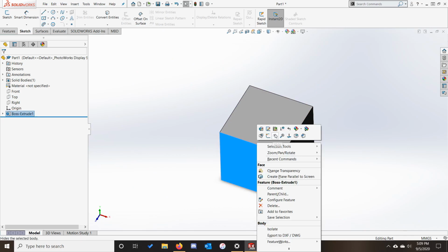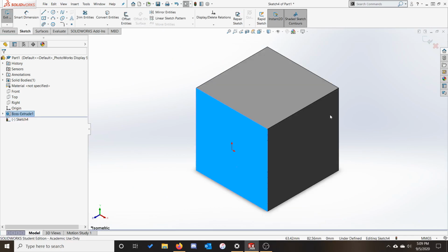As an added bonus, no matter which surface we open a new sketch on, the origin is going to be right in the middle, which can give us some nice references for future usage. The moral of this story is that properly setting up your initial sketch and being clever with the end conditions for your first feature can give you more usage out of the things that we already have.